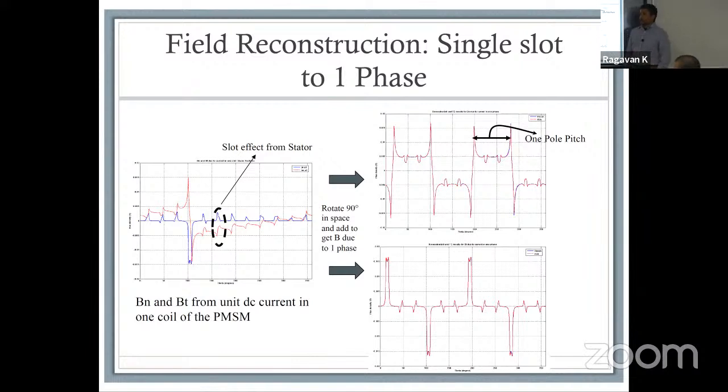What will be the reason of mitigation of one of that dip in the three phases? So we're not trying to mitigate the slot because the slot geometry is something that exists. You can change the slot geometry. In our case, what we were trying to do was minimize normal forces. That's perhaps one distinction I should make: oftentimes we combine the idea of flux with force. It has a direct correlation. Flux directly leads to force generation.